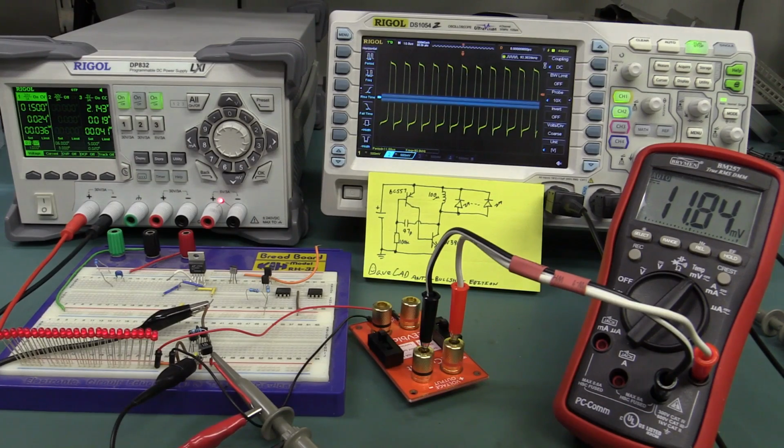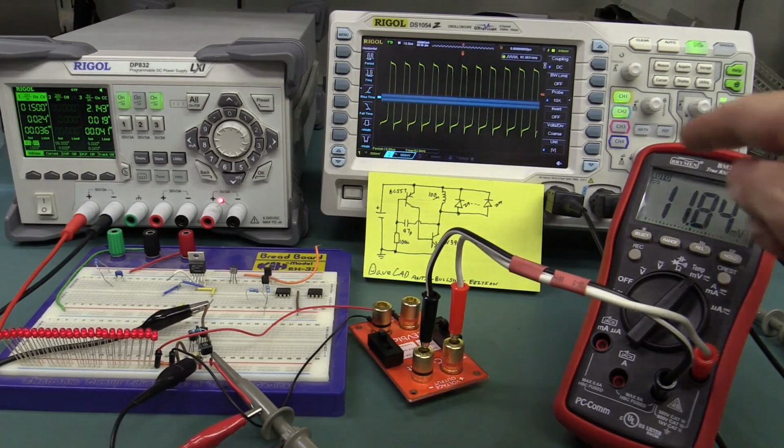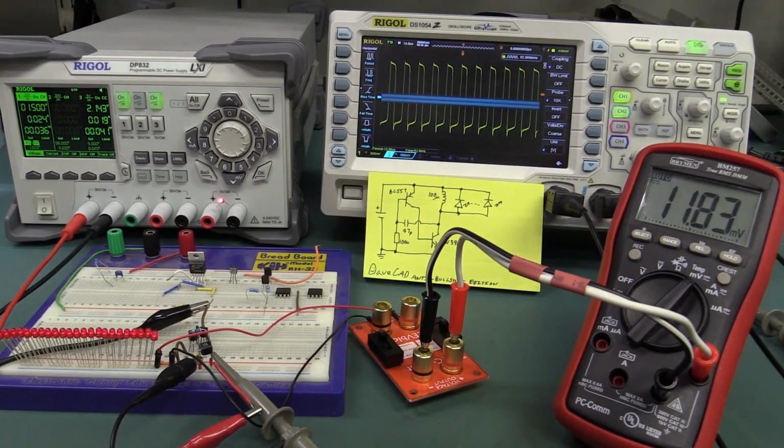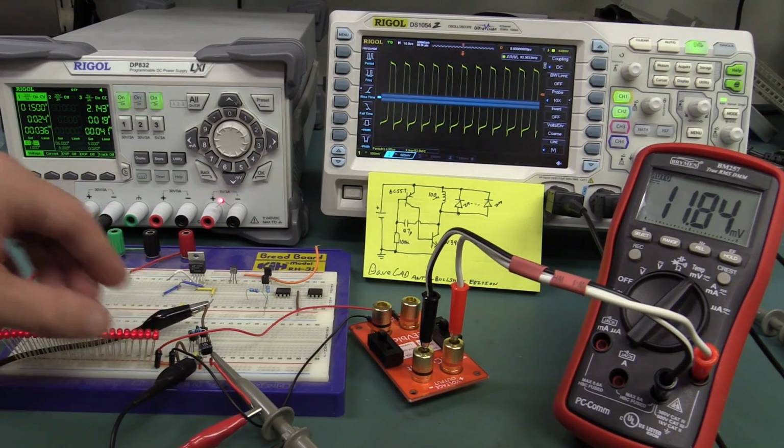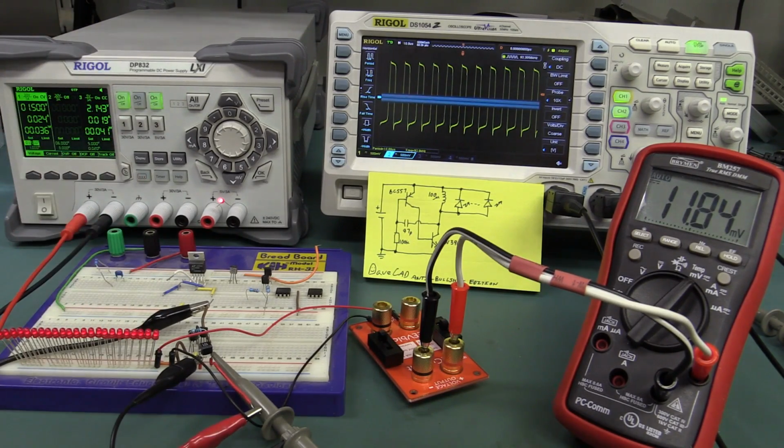So overall, our circuit is actually pretty poor in efficiency. It's only about 50% or thereabouts, because as you saw, we've got a total average current of 24 milliamps there, and we're basically getting like half of that, 12 milliamps or so on average, going through the LEDs. So yeah, you know, not that great.